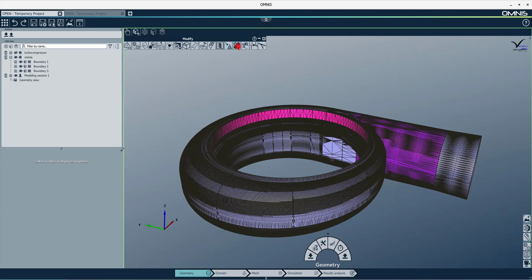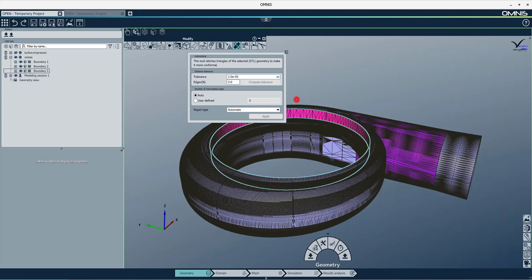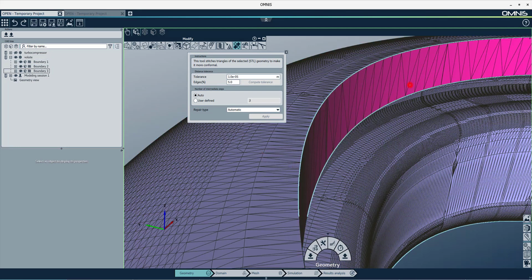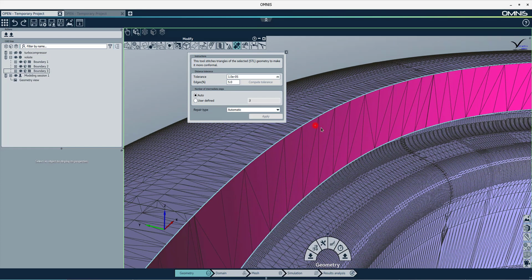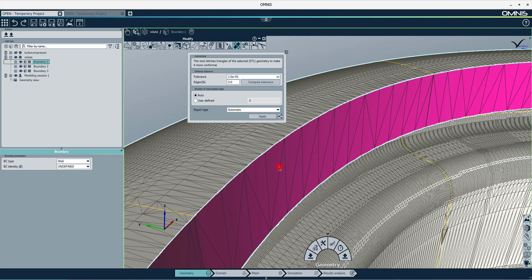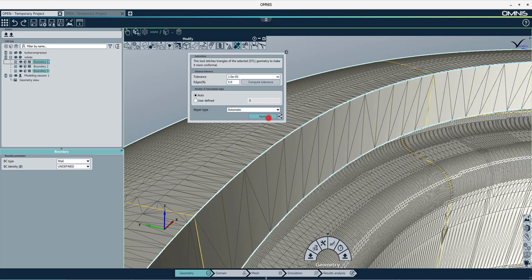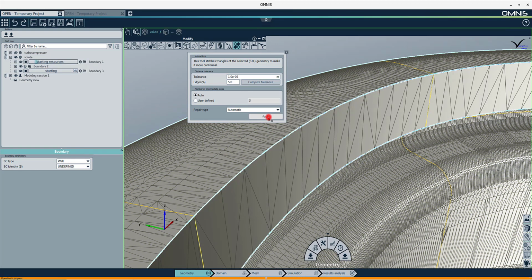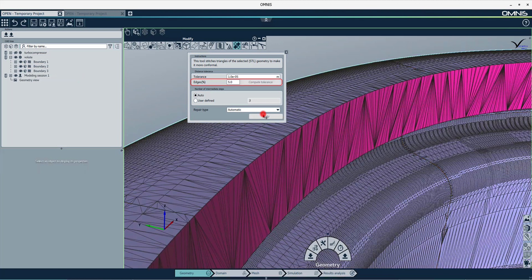Conformize Geometry conformalizes the triangulated geometry of an STL by performing stitching on the free edges found. This can be useful because in general, conformal geometry will have better geometry capturing during the mesh generation. The stitching algorithm will not treat the edges pertaining to 3 or more surfaces. You can use an absolute distance tolerance to merge the free edges separated by a distance within the tolerance, or you can compute the tolerance based on a percentage of geometry edges.